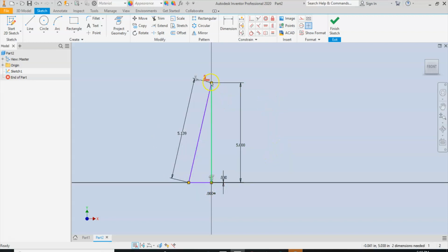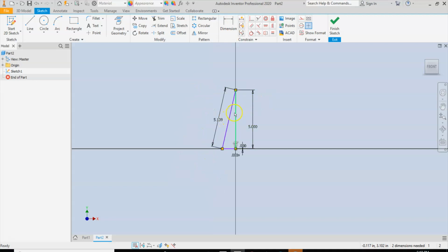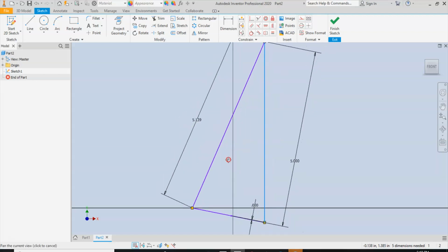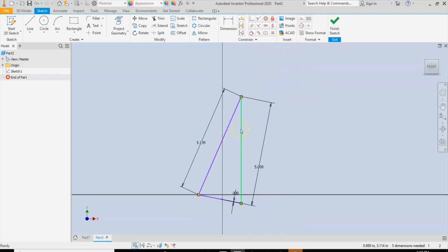You can change them. If I wanted to move this point here, I'm probably locked down, I'm locked down at 0, 0 on that. But if you wanted to change some of those features, I'm sorry, I'm trying to do two things. If you wanted to change that angle and not have a vertical line, you can make that change by removing the constraint. So right here I've removed that horizontal constraint, so I'm not locked in on that horizontal constraint.